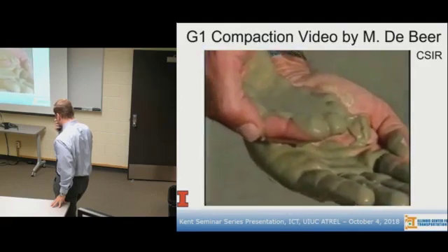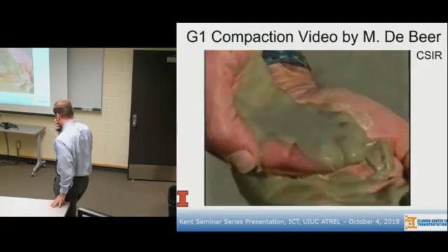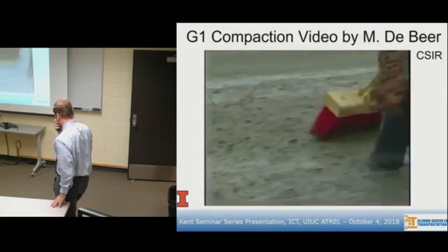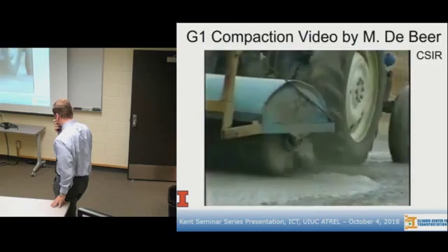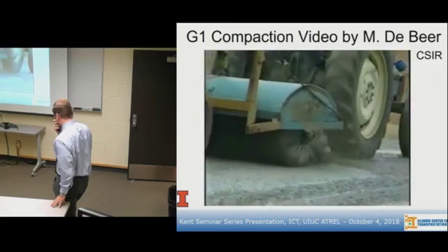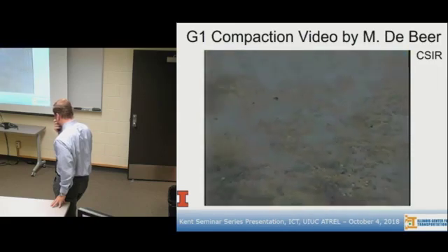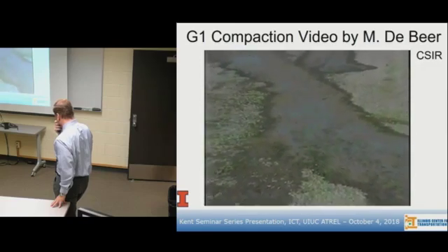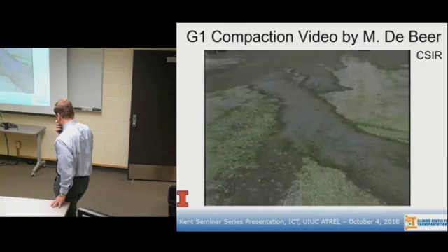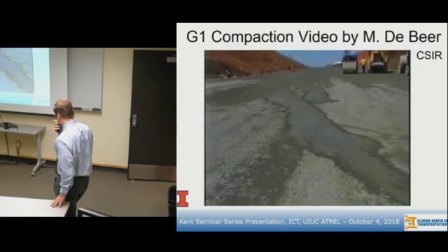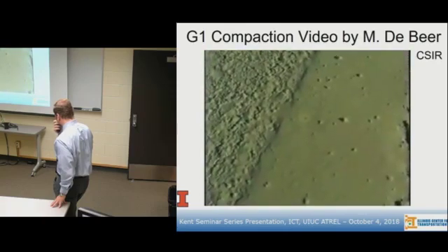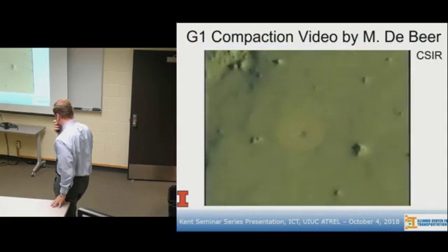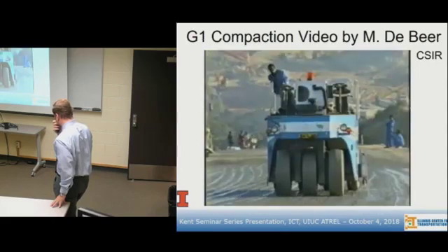The fines form a finely textured, tacky film on top of the crushed stone layer. These must be swept off the road by hand brooms or mechanical rotary brooms. Towards the end of the slushing process, the expelled water loses its coloration, indicating that the excess fines have been removed. Air bubbles forming on the surface behind the roller wheels indicate that there are still voids in the layer.